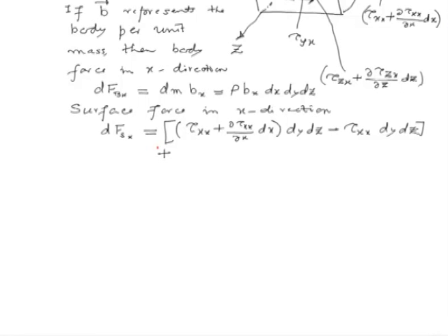Next, the force due to the shear components, first the ones on the y planes. On the negative y plane we have minus tau y x dx dz, plus the component acting on the positive y plane, that is tau y x plus del tau y x over del y dy into dx dz.